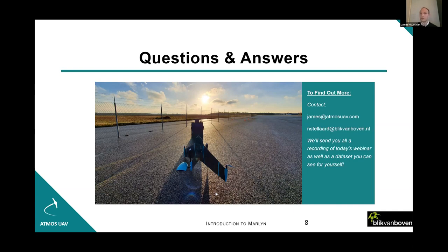What I saw in GeoTagger is that you can handle a lot of various types of data. Well, we use an M-unit, for example, like you mentioned, but there are several types of units you can handle there. As far as I understood, you need to have Rinex data. But it's possible to convert. So you have a Rinex, I think it's a .T05 file that you get from a Trimble base station, and then Trimble has a free to download software that you can use to convert .T05 to the Rinex, and then it's possible to put into GeoTagger.